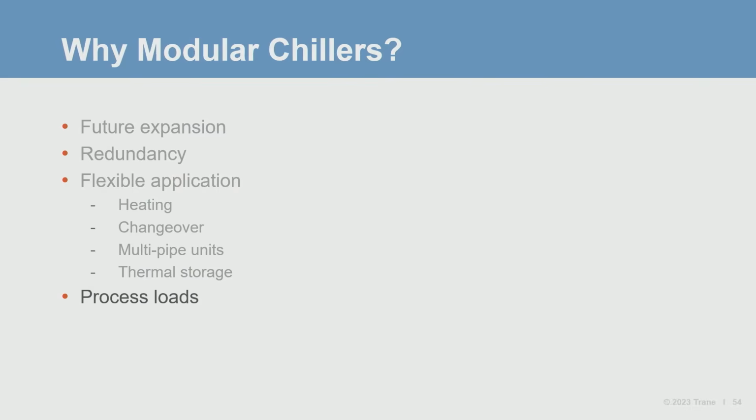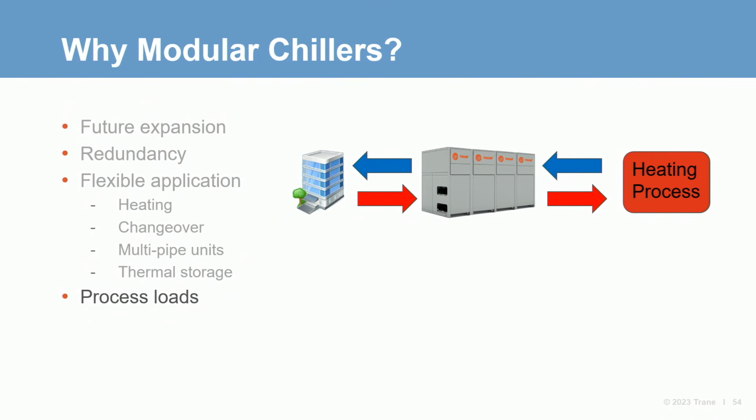And speaking of heat recovery, let's apply that concept to a process load. A process may have a dedicated chiller, or multiple temperatures may be required for several processes. Heat energy may need to be added or removed. A given heating process load might be fairly constant throughout the year, so there may be a consistent sink for heat removed from a building. We can leverage that process to reuse heat removed elsewhere, or vice versa.